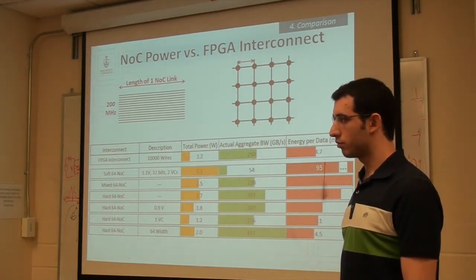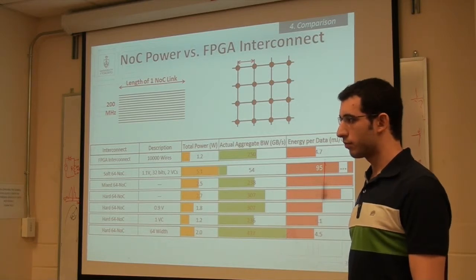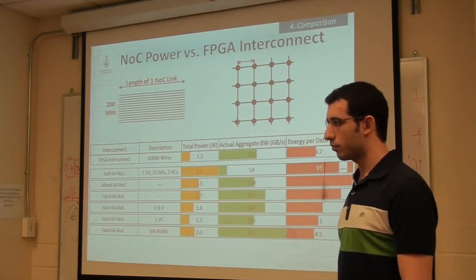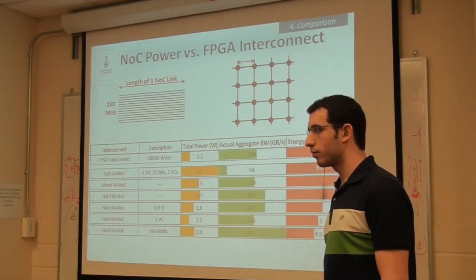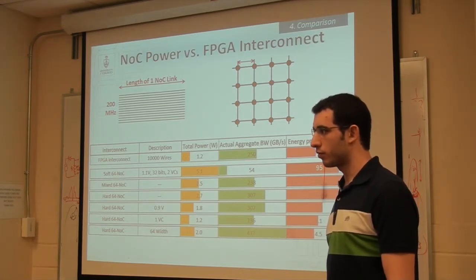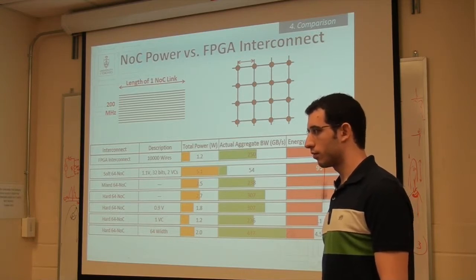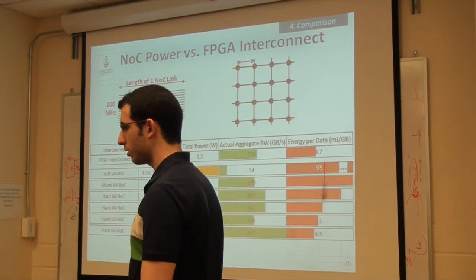That's one thing. Even if you use latency-insensitive design, you've taken care of the problem of closing timing and basically having latency with regards to correctness and operation of your design. When you do latency-insensitive design, no matter how fast stuff runs, you will theoretically close timing. So with an NOC, your latency is now variable depending on how far apart your endpoints are, because it'll change the number of routers you go through.